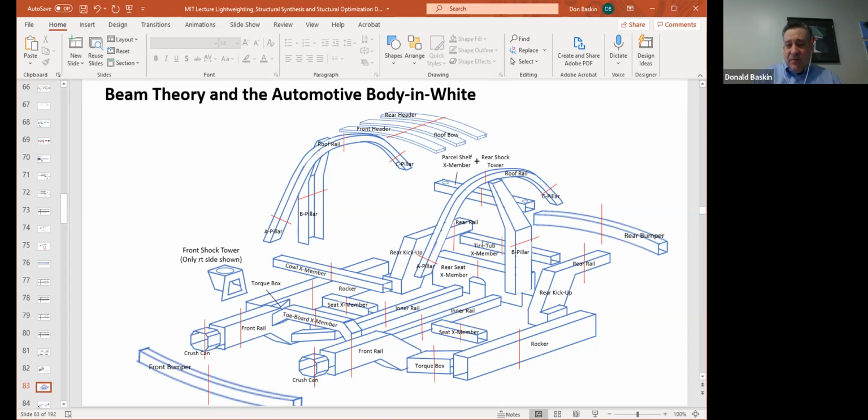Another thing to think about is how much this car weighs. These cars are really, really heavy. I mean, they're like 4,000 or 5,000 pounds. And I think their goal is to get 3 to 5 times the weight of the vehicle in strength out of the roof structure, so that if the car is inverted, it can support 4 to 5 times the weight of the vehicle before there's any plastic deformation in the roof structure, right? So you have to have a lot of strength up there.